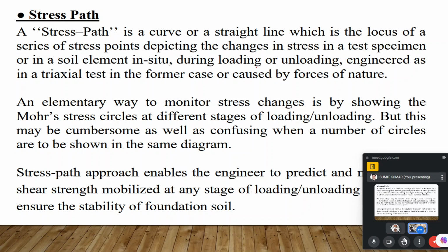Okay, so I will start with the stress path. A stress path is a curve or a straight line which is the locus of a series of stress points depicting the changes in stress in a test specimen or in a soil element in situ during loading and unloading, engineered as in the triaxial test in the former case, or caused by the forces of nature.